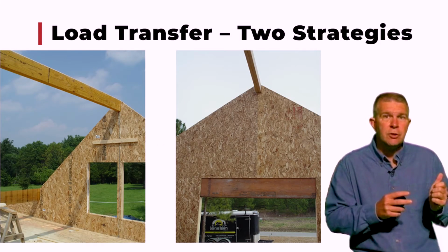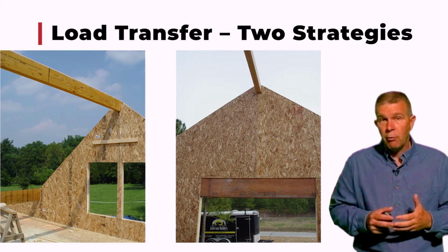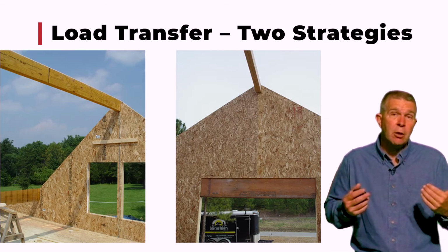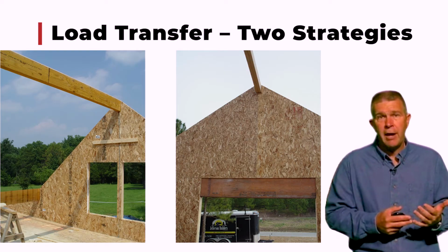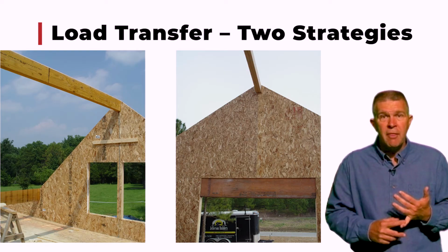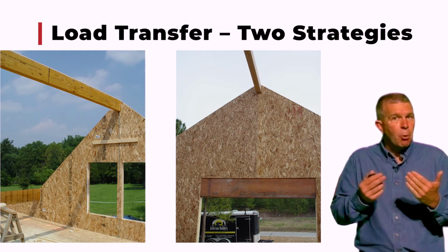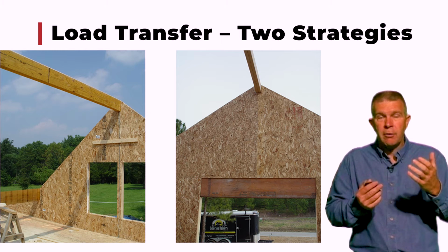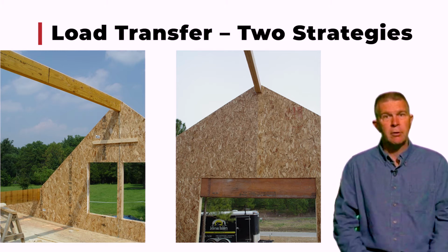These photos that you see are two different ways to carry point loads down through a wall panel. And in these pictures, we're also showing how the point load carries down to and around window openings. The picture on your left, obviously we have a large ridge beam. That ridge beam comes into the top of the gable wall, and where those gable panels come together at that point, we are carrying through posting all the way down through those two windows down into the floor system or